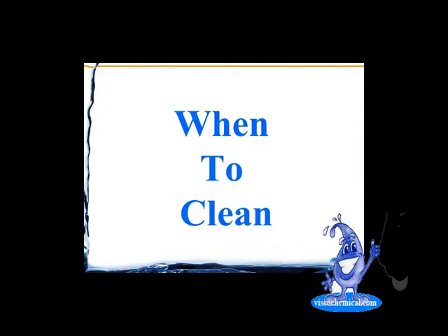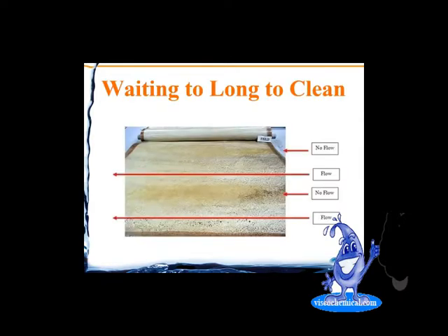For fouling, fouling can occur continuously, especially on surface waters. Fouling on a nice deep well water usually isn't a problem. But when we do foul and we see that the feed pressure is going up and the pressure drop across the first stage is going up, then it's going to be time to clean. Well, how do you decide when it's time to clean? That's what we're going to talk about in this section.